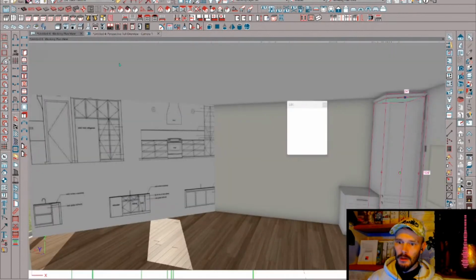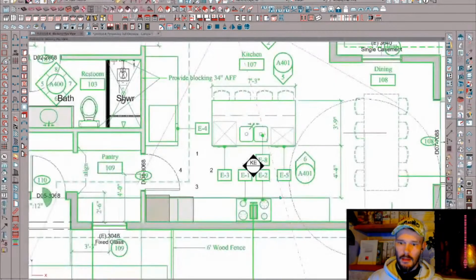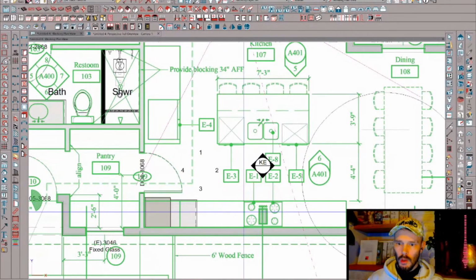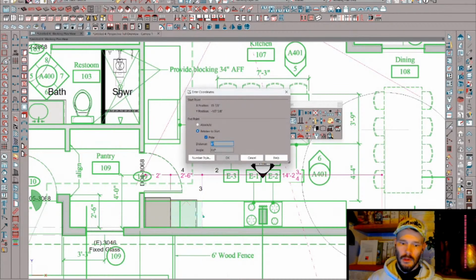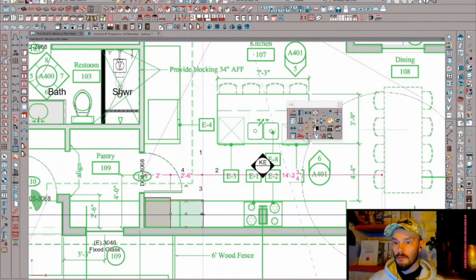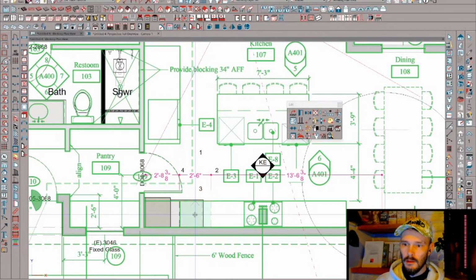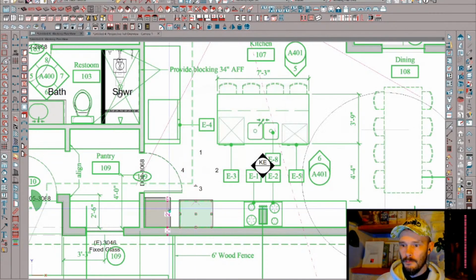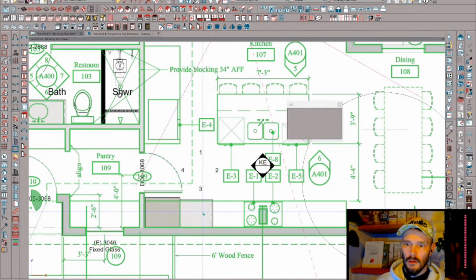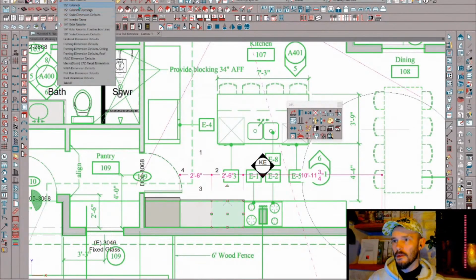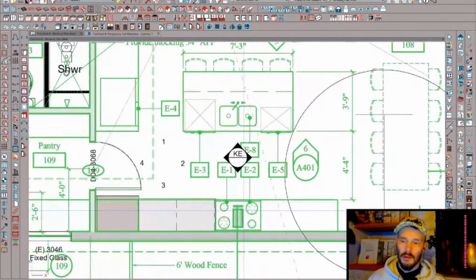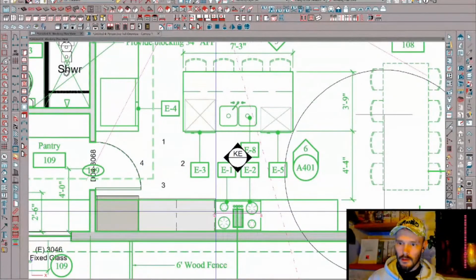So we know from this that there's only 2 cabinets there. So let's just do a little measure. 60 inches. So they're 30-inch cabinets. Which makes this what? 6? And that's going to be 9. Switch my dimensioning defaults here. That makes it easier on me. And that was a range, right? So, and what is that? Is that a 36 range? Looks like a 36 range.